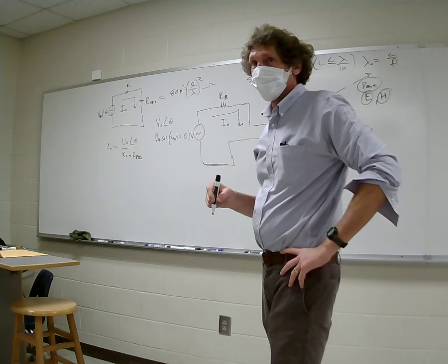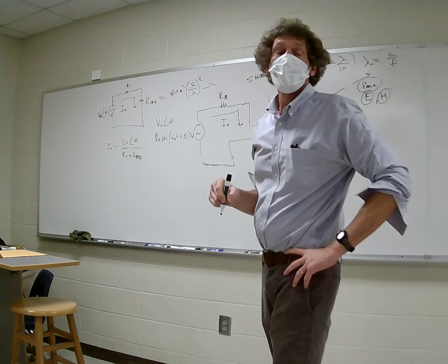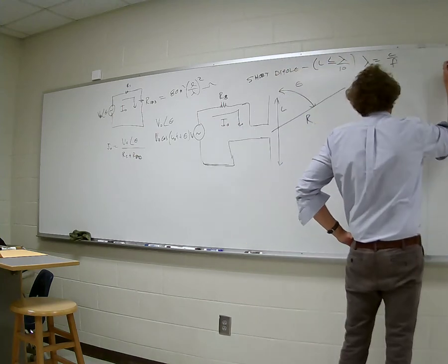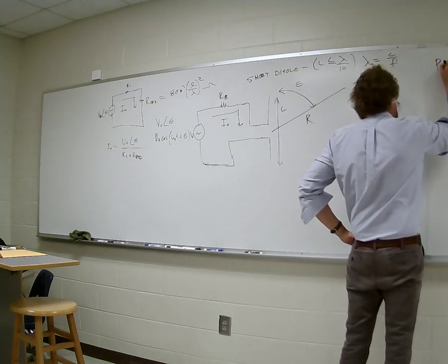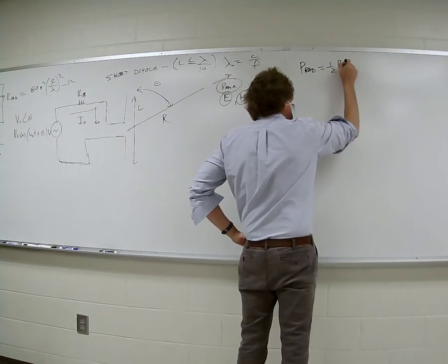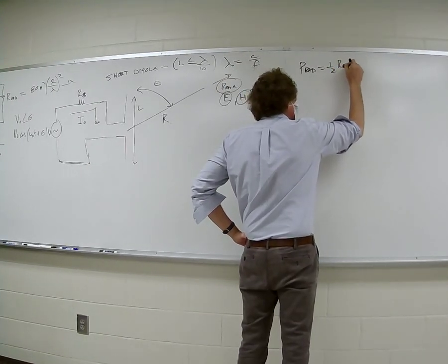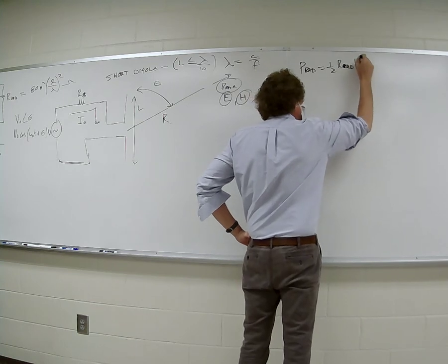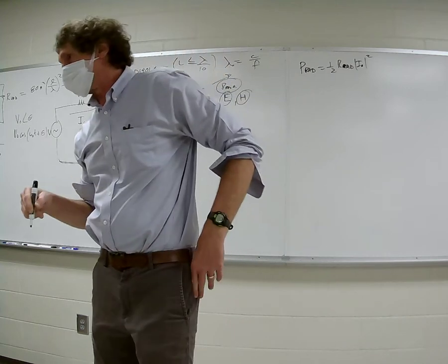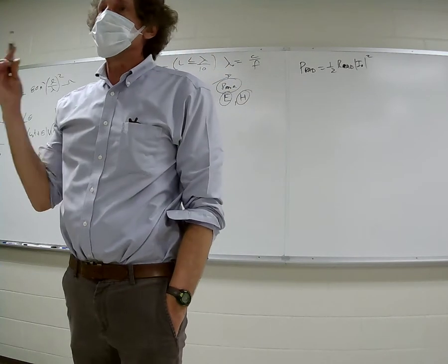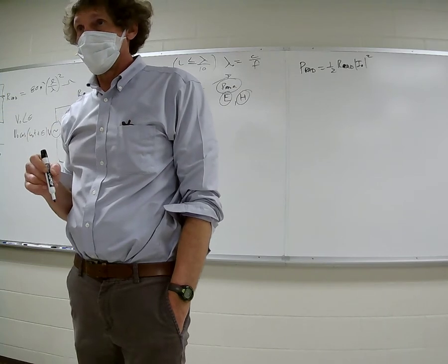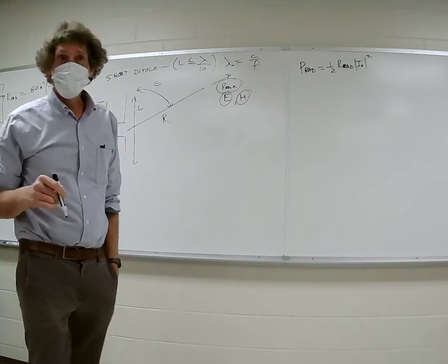Radiated power. Yeah, how do we get the radiated power? 1/2 R_rad times I naught squared. 1/2 times the radiation resistance, right, times the magnitude of I naught squared. Make sure you put magnitude down there because you get a real and complex number. If you have a real plus j imaginary in your calculator, it's strict magnitude, got it? So now we have P rad.